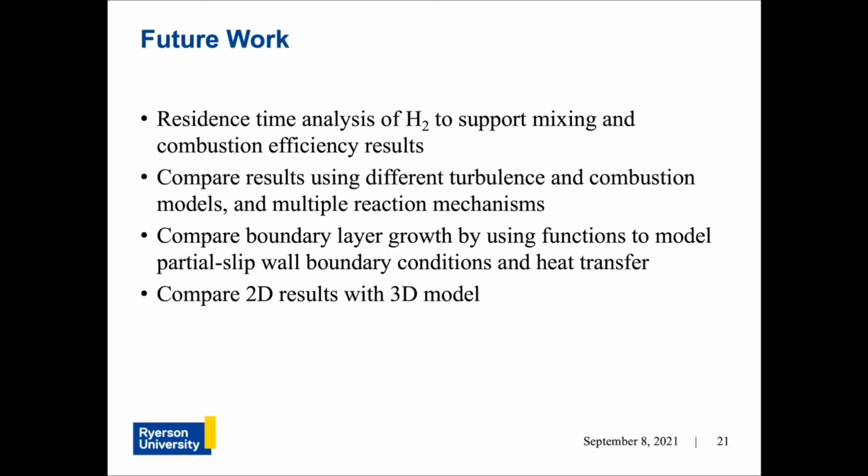Since complete mixing occurs before the combustor exit, the potential for reduction in total pressure loss by shortening the combustor can be investigated. Also, residence time analysis can be done to support the results of mixing and combustion efficiencies. Different combustion models and multiple reaction mechanisms instead of this one-step hydrogen-oxygen reaction can be simulated and compared against experimental data. The boundary conditions along the walls can also be refined to include friction, partial slip, and heat exchange, which may affect boundary layer growth and thus the internal flow field.